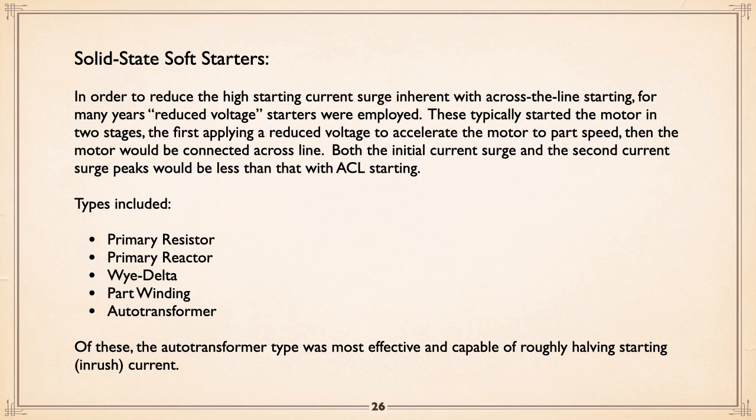With an auto transformer, basically it's a transformer hooked up. It's not purely isolated. They have one of the leads common across from both the supply side and the utility side. What it does is basically transform the power down, and with a centrifugal pump, because all the action happens as speed comes up, the ideal setting was around 65%. They had taps at 50, 65, 75, something like that. But 65 was the ideal one.